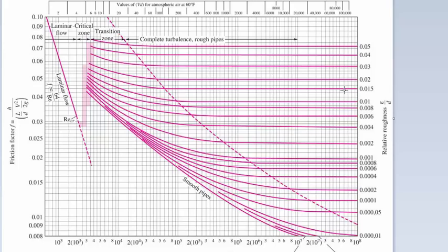And the way we get our friction factor is we have to use this Moody chart over here. On the right-hand y-axis, you'll see the relative roughness, which is that pi group we were talking about before, epsilon over D. And our Reynolds number is down here along the x-axis. So if you remember, our relative roughness was just about here.